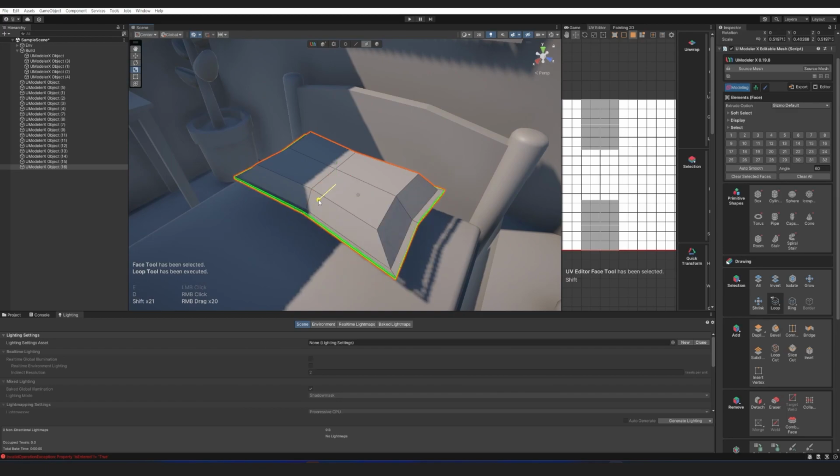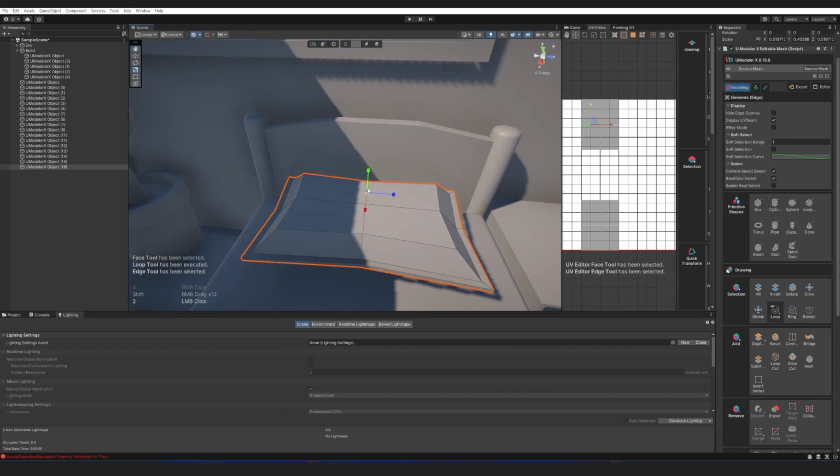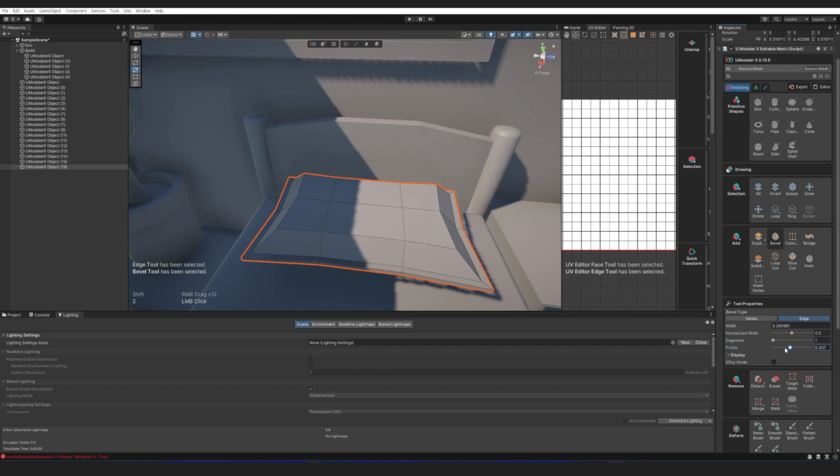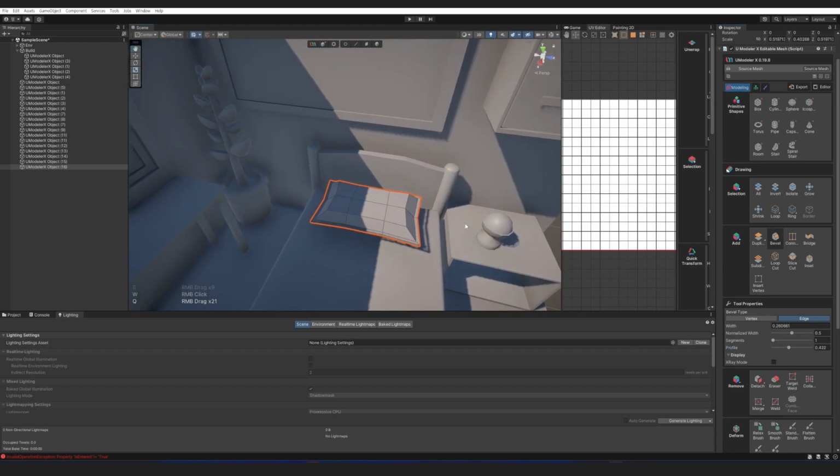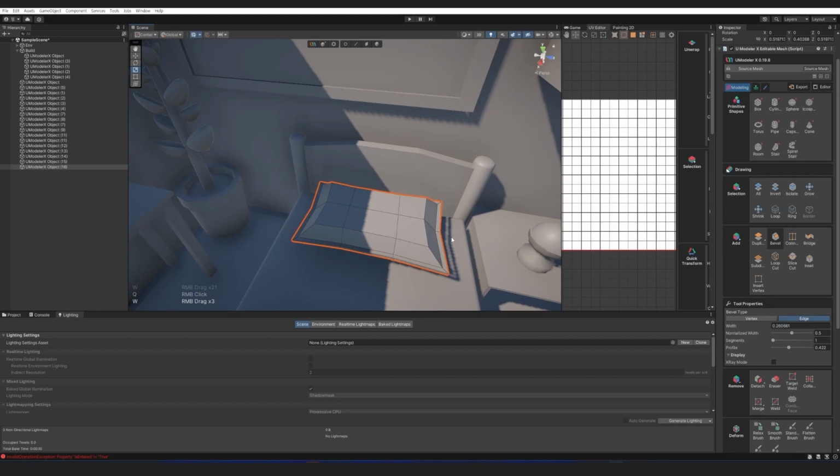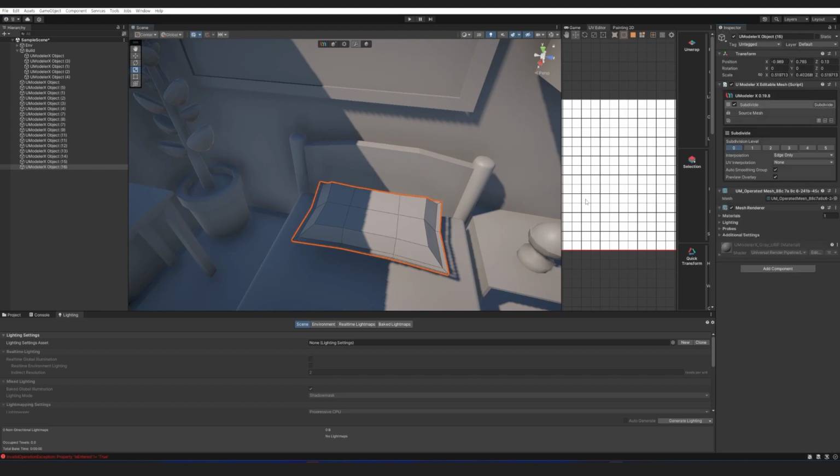It still looks like a blocky pillow. Use the subdivide modifier to double the faces and create a smoother object. Activate the subdivide modifier and select the multiplication factor. Be careful not to create too many faces as it can overload the memory. We select the steps of subdivide to increase the faces. If the result is not as desired, uncheck the box to revert or click the minus button on the right to remove the subdivide function.